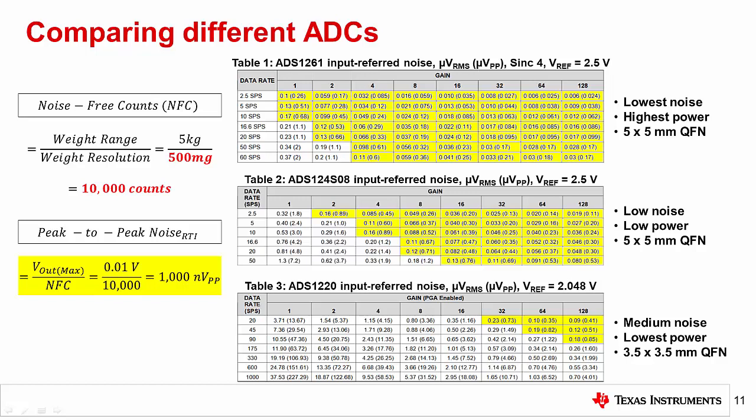This also helps explain the true benefit of a high-resolution ADC. Even though our example system only needed 15.3 bits of resolution, it required a 24-bit ADC to meet the target. While you might conclude that you're paying for ADC performance you won't actually use, you're actually taking advantage of a noise floor as low as 24 nanovolts peak-to-peak in the case of the ADS1261. This is an incredibly small value which no 16-bit ADC and few 24-bit ADCs can provide.